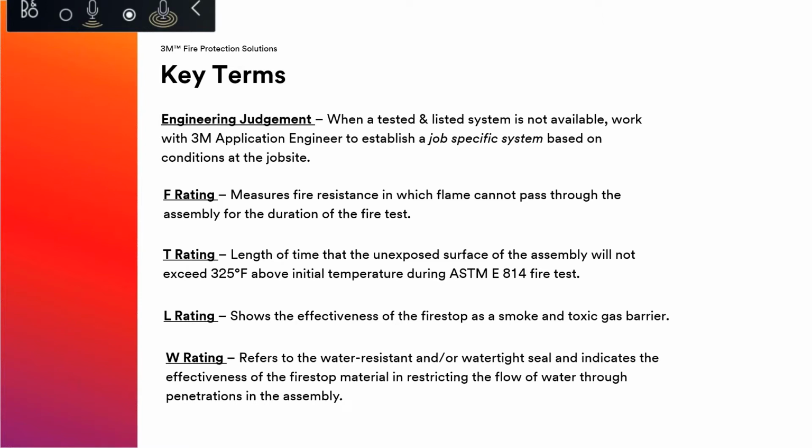But T ratings and F ratings and L ratings, which L rating is your air leakage, your smoke seal, those three are the most heavily enforced, especially the F rating, those three are the most heavily enforced criteria out on your projects. Then with W rating, unfortunately, I missed it on this slide, in addition to that would be your W rating and your M ratings. The W rating is the water resistance or watertight seal in addition to your F, T, and L.